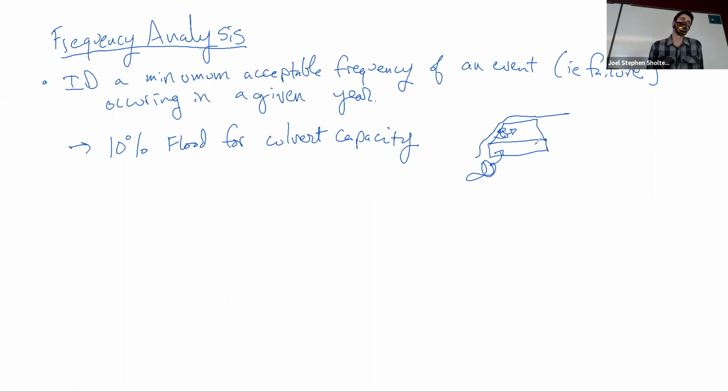But you could also design for that too. Maybe it's expensive to put in a culvert that conveys the 100-year or the 1% chance flood. So we'll do 10. And then maybe we'll just design the road so that if it gets overwhelmed and it's really important that it doesn't wash out, it's okay if it's flooded for 6 hours or something like that. Then we can design the road to not fail when this culvert's overwhelmed. So we can mitigate that risk, but save ourselves some money because culverts are expensive.